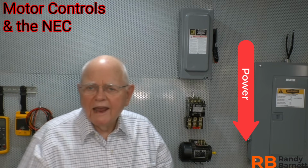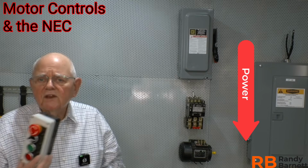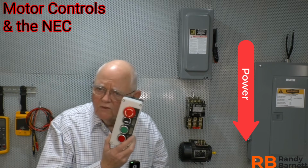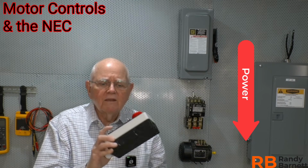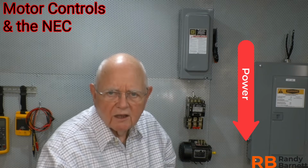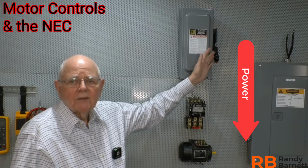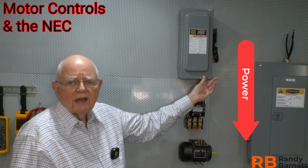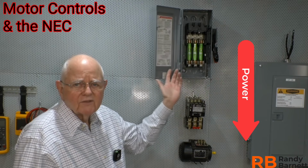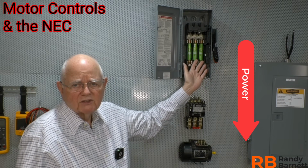Something that I want to have associated with controlling and operating this motor is some type of remote control and signaling circuit, right? So I want to be able to push a start push button somewhere else out in the plant and cause this motor to operate. So I have some type of disconnect switch, and I'm going to have some fuses in here. Now the fuses are for short circuit and ground fault protection, aren't they?